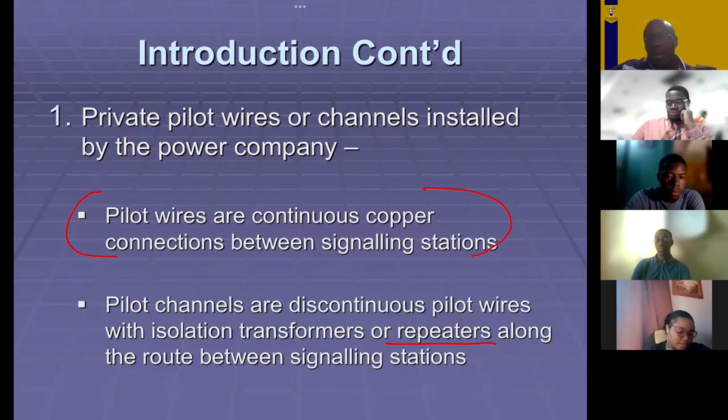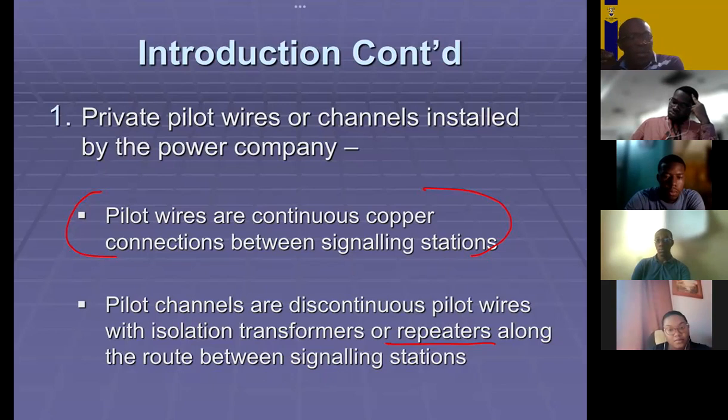So it means that you can have a signal being superimposed on that copper, although you avoid that by using twisted pairs, but you can have noise, which we refer to as unwanted signal, being superimposed on the copper pair. So when it gets to the repeater, unless the value that it sees is above the threshold, it will put it back to 1. Because what you want to pass on are clear 1s and 0s. Am I clear?